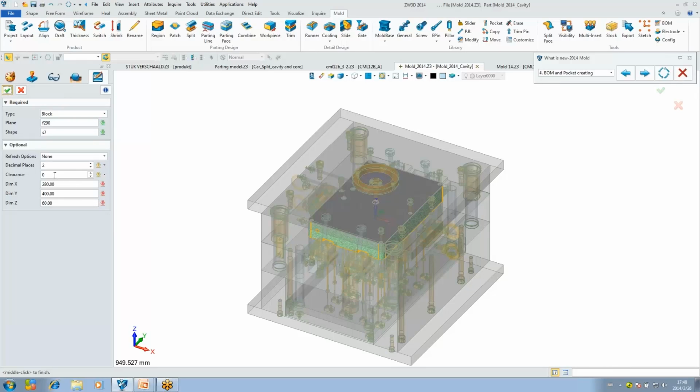What's more, in the new version, we support defining the decimal place or the clearance. Right here we can set the decimal place to 1. So here you can see the XYZ direction values have been changed, and we can also change the clearance, because most of the time the workpiece for the part we always need to make a little bigger.